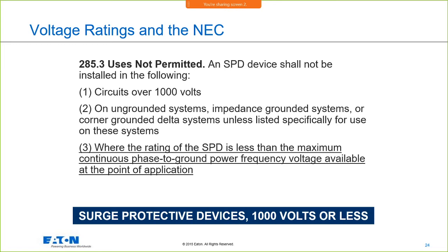We have circuit breakers that do a dual function in that regard, where we have say a 60 amp or a 50 amp thermomagnetic 2-pole breaker that also provides surge protection. So it does two things.